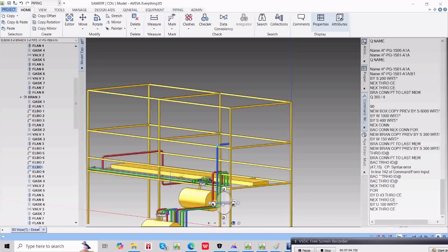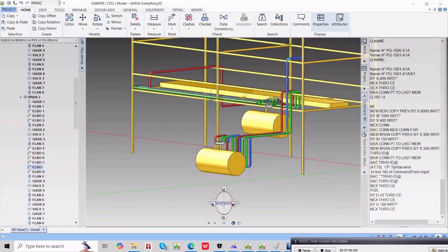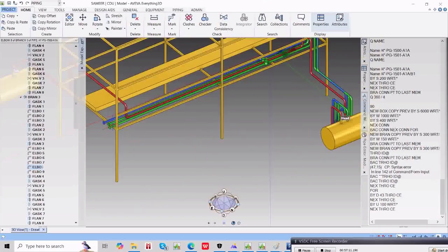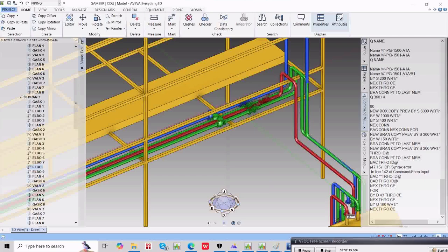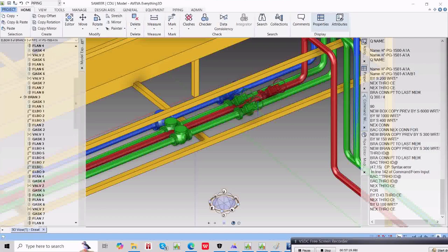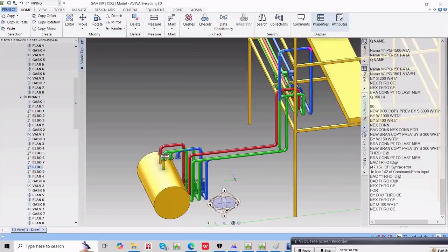Okay, the purpose of creating these intermediate members, and the purpose of creating this staggering and all, the purpose when you are going to, what type of valves you can use in the pipe rack, it doesn't require any maintenance. And if you have any valve which requires maintenance, that has to be at the corner, so that the person can put a temporary ladder and can use it. Okay, then headroom clearance, valve assembly either next to the equipment or under the pipe rack. So all that you need to consider as per your layout requirement.